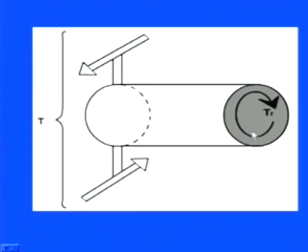The torque is trying to rotate in this clockwise direction, as I told you, and we have another portion. If we want to make this segment an equilibrium, then we need to apply torque in an anti-clockwise direction. So this is one significant effect. The middle portion is also affected by the rotation. The layers of the circumference of this particular cylinder will always tend to move in this direction. There is no elongation in the x direction or y direction; they simply tend to move along the circumference.